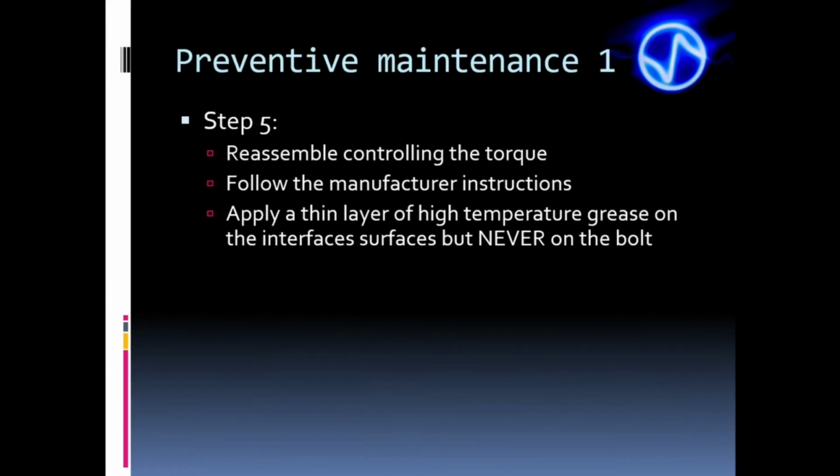Here, an important observation. It's common for users of ultrasonic machines to retighten the stack, increasing the applied torque as it starts to show lower efficiency because of wear. And often it works, doesn't it? But what happens when we apply more torque is that we correct the poor coupling and surface wear by crushing those grooves and scratches with the high torque pressure.